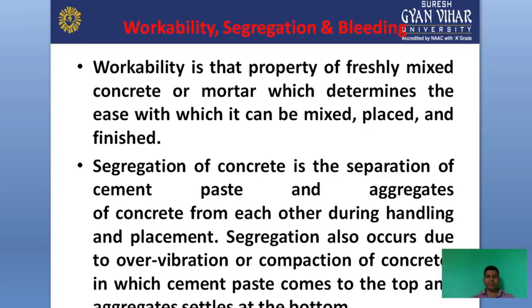Segregation defines the separation of cement paste and aggregate in concrete. As you know, concrete is the mixture of cement, sand and aggregate. The separation of the components, like aggregates from cement paste, during handling and placement, that process is known as segregation. In simple words, we can say that it is the separation of particles, the separation of components in cement paste during the mixing or placing of concrete.